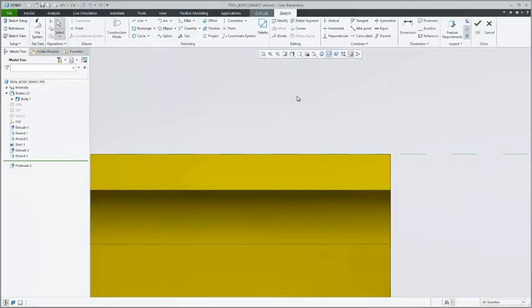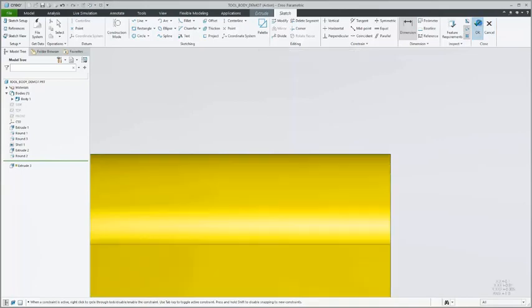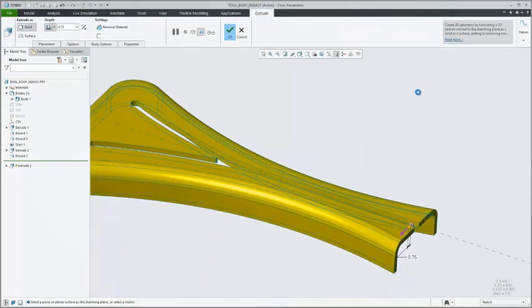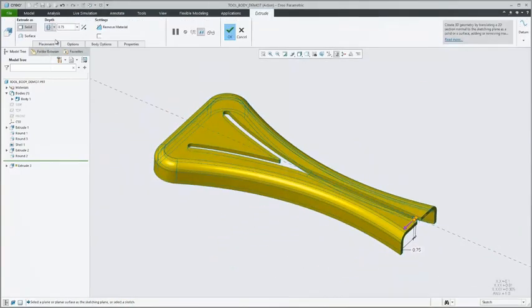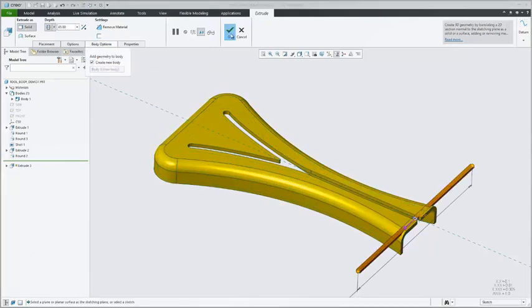Here we have our design part, where in the following we want to create grooves in that design part as we had seen on the previous picture. There are various workflows to do this. The fastest and most obvious one that we want to illustrate here makes use of a second body that will be used as a tool body to modify the geometry of our design.